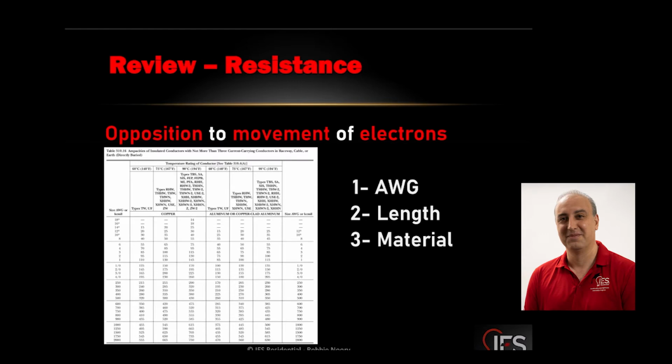Now, regardless of the table, almost every table in the NEC book separates copper and aluminum. So when you look at your tables, like this ampacity chart, if you go to 310.16 in your book, you see the first 3 columns are for copper. The next 3 are for aluminum or copper-clad aluminum.